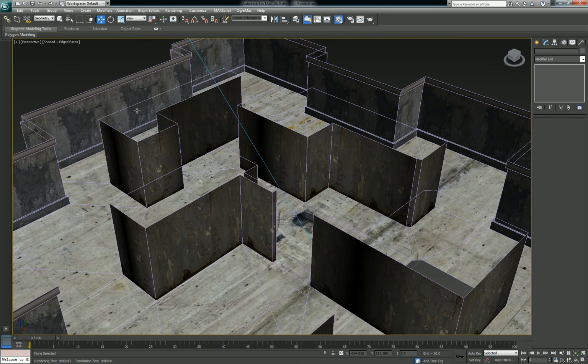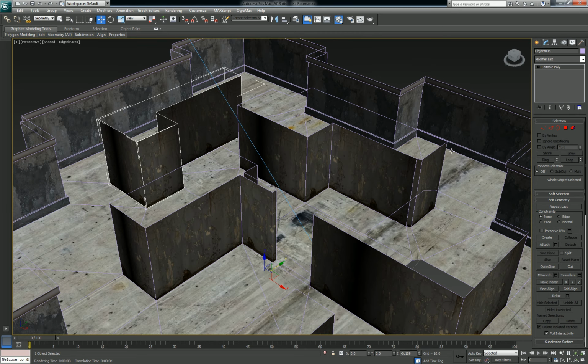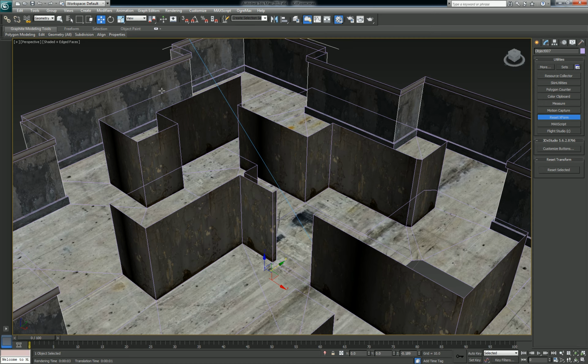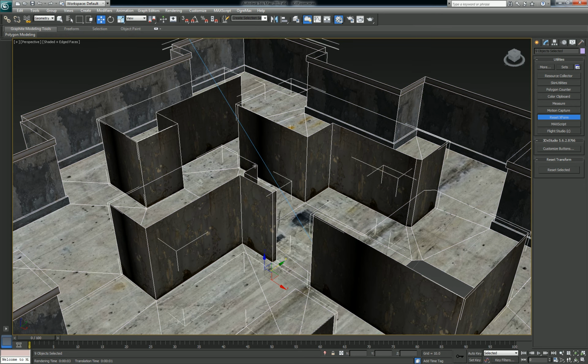As normal habit, once you've more or less created your base, you want to validate and verify the normal directions as well as the true scale of your scene. So what I'm going to do is select my select type to geometry, and I'm going to select all, Control A, and go over to the utility tab.